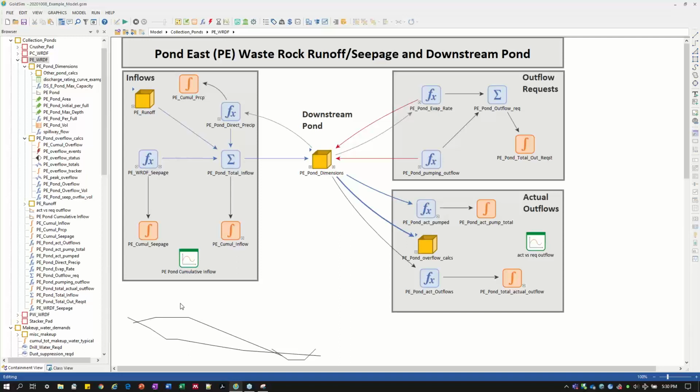because the goal at the end of this design is to establish vegetation, try to shed as much clean water off this as possible. So there's actually 3 different runoff calculations happening over time. And then there's also the seepage, and the seepage varies depending on if this waste rock is exposed or whether or not we've put a reclaimed cover that helps minimize how much water is going to come through.